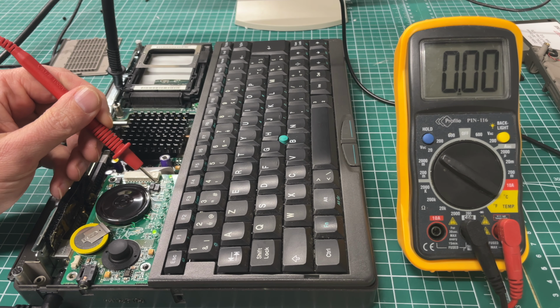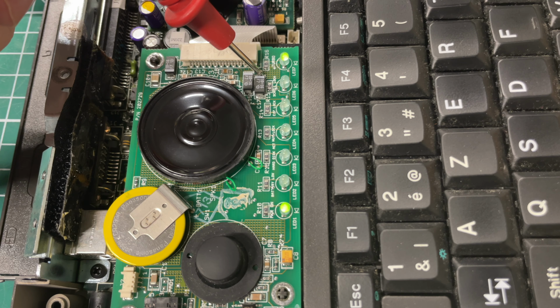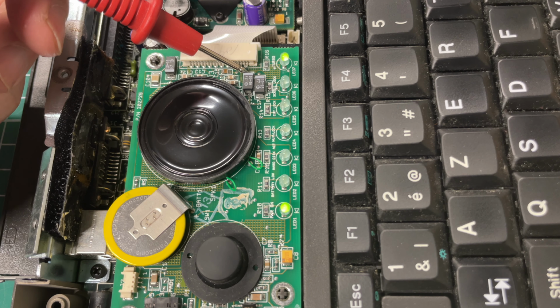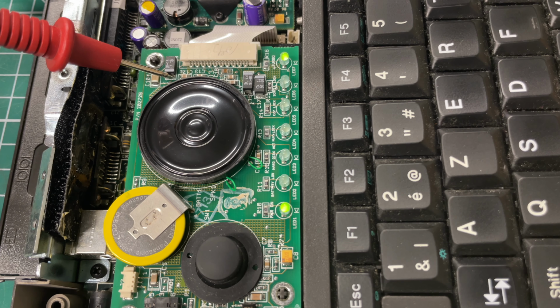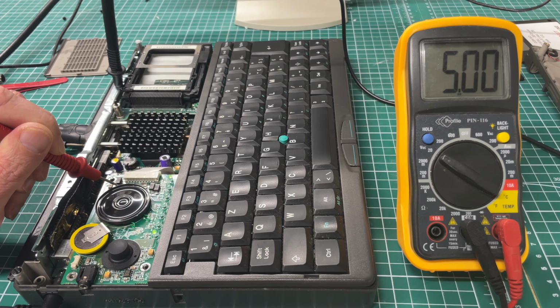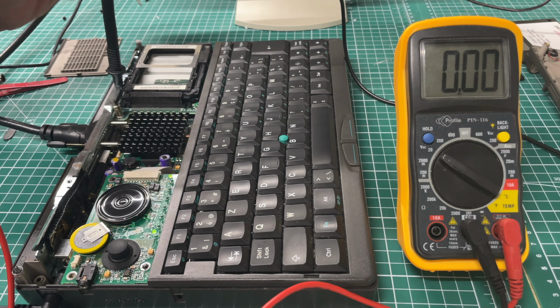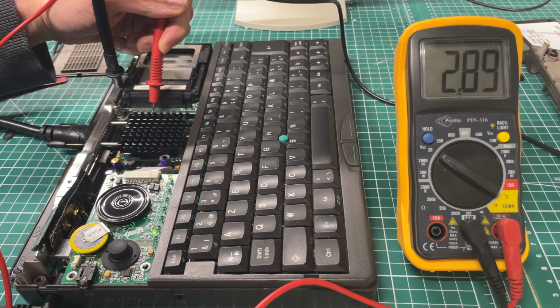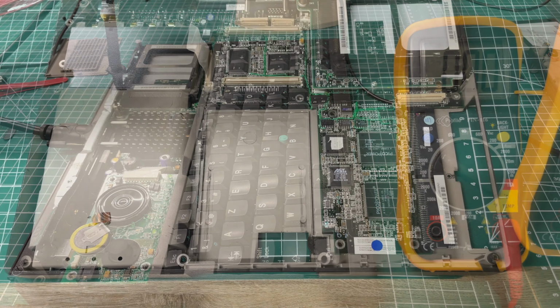And when the machine is actually running for a prolonged period due to some miracle, we do see rather clean voltages on the caps here on this daughter board, and also on the CPU itself. When we measure the voltage there, we see a clean 2.9 volts, allowing the machine to basically work the way it should.